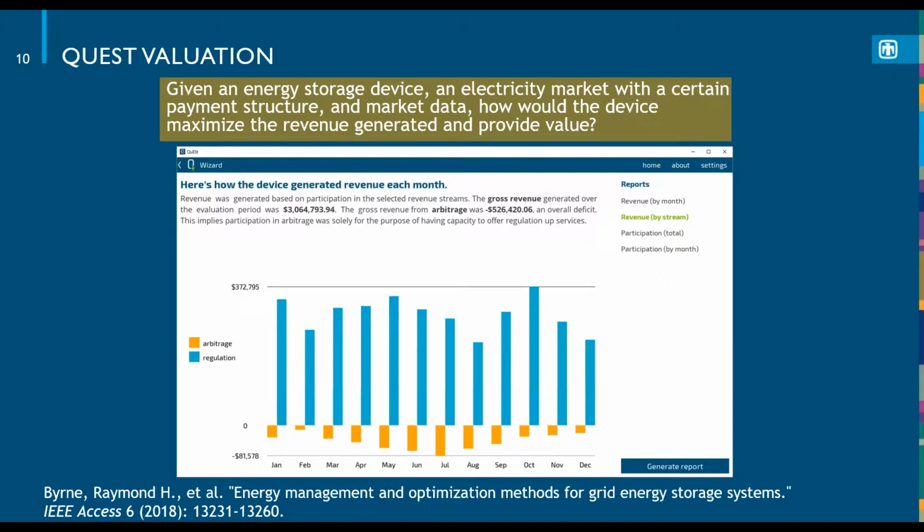It uses a set of historical data, say the calendar year of 2018, and looks at 1 month at a time. In each month, the energy storage system has what we call perfect foresight of the prices, in that it knows in advance the prices for all value streams at each time step. We then formulate an optimization problem in which the system determines the optimal policy of bids or transactions in order to maximize its revenue over that month. As such, this procedure estimates an upper bound on revenue potential over that time period.